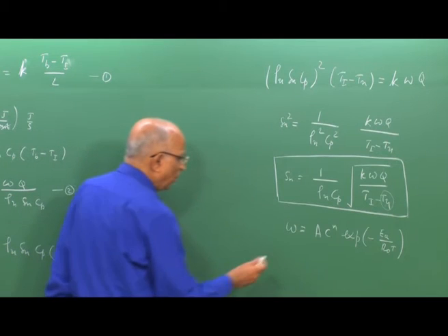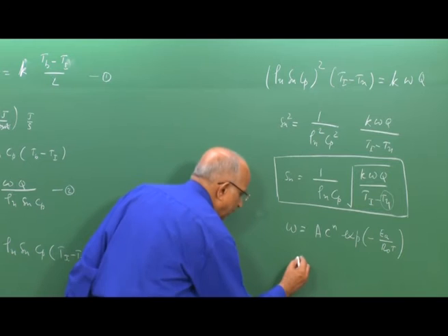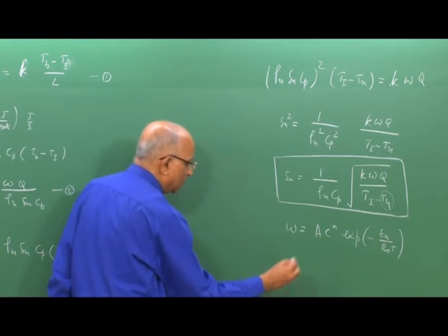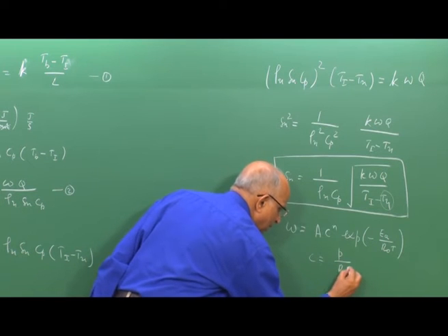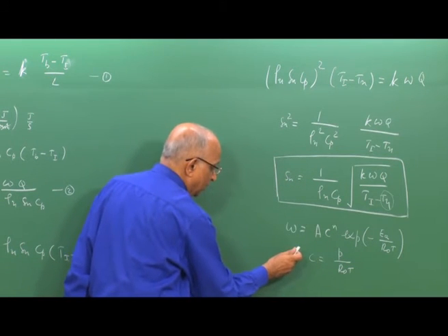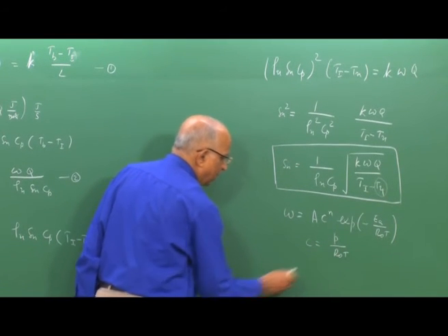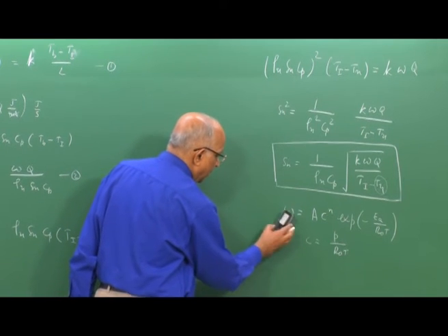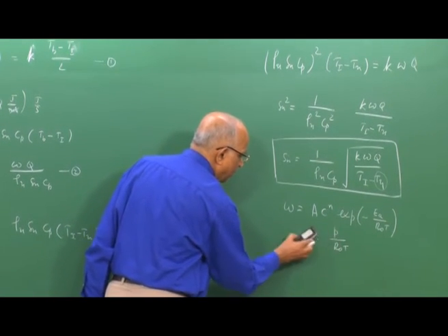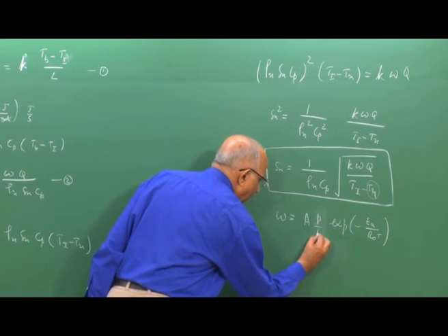And we also know, well, we are considering a gaseous mixture for the present, and therefore, I can write PV is equal to n R0 T, or concentration is equal to P divided by R0 T, because PV is equal to n R0 T, concentration is n over V, which is P over R0 T. Now I can write the rate of a reaction: I replace C by P by R0 T, and what do I get? I get P by R0 T to the power n over here.